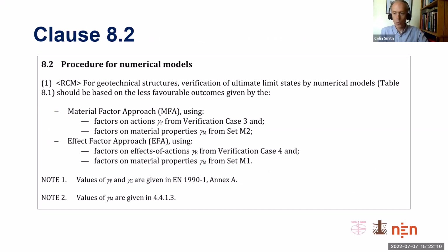In terms of text, this is what we have in clause 8.2, which outlines the procedure for numerical models, and effectively that's just saying in words what I've just gone over in the previous couple of slides, looking at the MFA and EFA approaches, and guides you as to the various partial factor sets. So we'll have a look at those partial factor sets, see what has changed, see what is relevant to numerical methods. One thing before I go into that, just point out this is a recommendation as to the approach that should be used for numerical methods, but it's not mandatory.